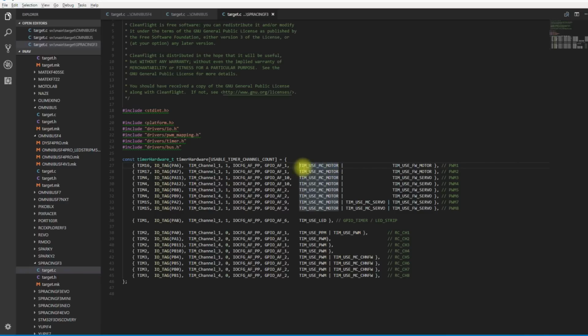In case of multi-rotors, this column here, all the outputs are used as motors because there will be no conflicts. But in case of two last pins, PWM7 and PWM8, it is possible to use those two outputs as servo outputs with completely different frequency than previous one. For example, for servo gimbal or what else, channel forwarding or whatever there is.